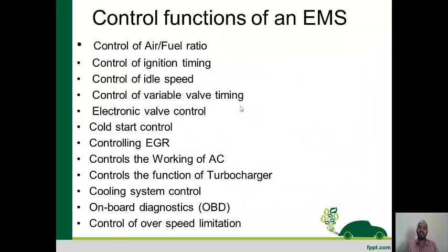What are the control functions of an EMS? An ECU, or you can say engine ECU, or engine management system, hereafter I will term it as the engine management system. That is nothing but the engine ECU. Based on the inputs and the program written, it will vary the air fuel ratio, the air quantity as well as the fuel quantity. There are different air fuel ratios like stoichiometric, lean condition, and rich condition. At some operating conditions one air fuel ratio will be used, and at other operating conditions another will be used.